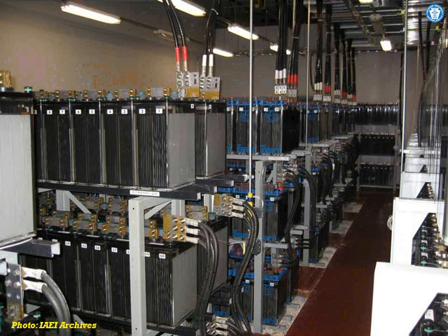You just flip the power. You start taking power from the batteries. You're paralleling this and the UPS? Is that what you said? You're inside the UPS, you're paralleling this source of power, the battery source of power, and the utility source of power, and the generators, if any. All these are paralleled inside the UPS at the DC level.